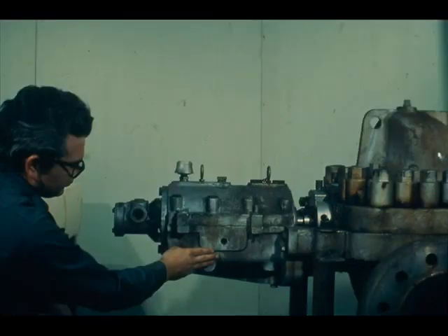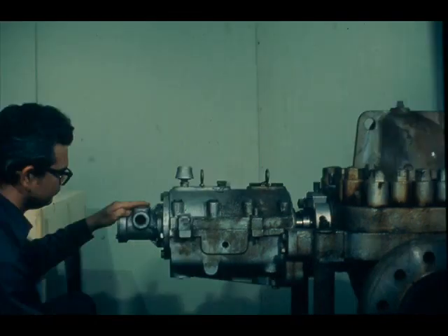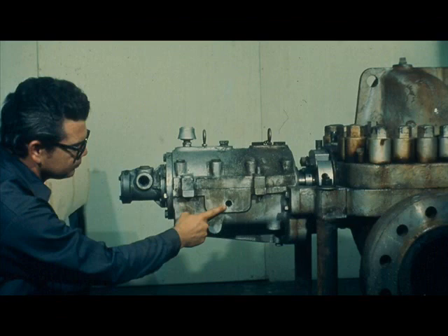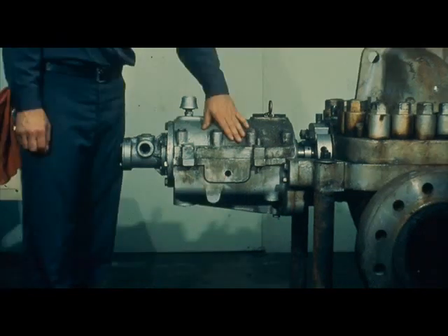The bearing housing is split horizontally, and the lower half of the bearing housing may be considered as an integral part of the pump case. The oil pump being pointed out here is driven by the pump shaft and supplies clean, cool oil to the thrust bearing through piping to the oil inlet connection shown here on the side of the lower bearing housing. The upper half of the bearing case bolts to the lower half as shown here and is aligned with dowel pins.